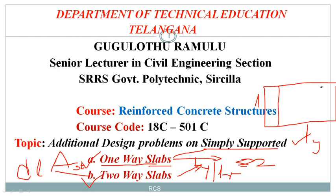That is, this is the edge, this is one more edge, and this is the middle one. So in the middle strip we have to calculate the area of steel, and the area of steel in the edge strip as well. Similarly, the slab is also divided in the shorter span direction, like edge span, middle span and edge span. So this is again called the middle strip region in the x direction, and this is an edge strip in the x direction, and this is also an edge strip in the x direction.